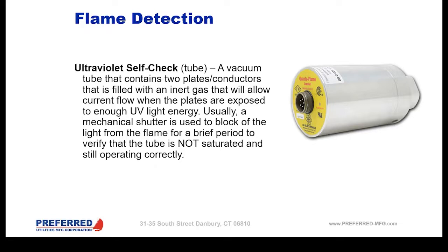Right, because it's that off cycle where the flame safeguard can detect a runaway scanner. It turns the burner off and it's looking for the scanner signal to go to 0. And if it doesn't, the flame safeguard will go into lockout and not light off again. Exactly. That's where it will indicate the false flame. And that right there is the troubleshooting that you would know immediately. Well, we got a false flame. When did this occur? And that will tell you probably had a runaway tube.